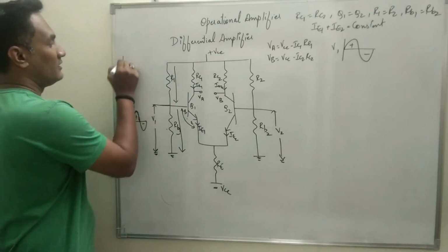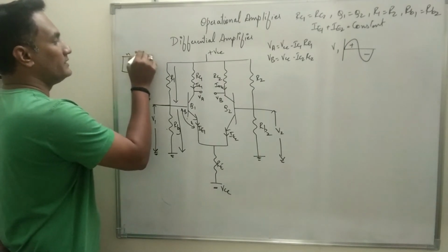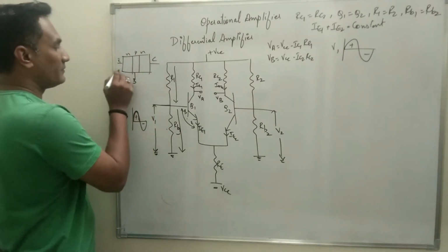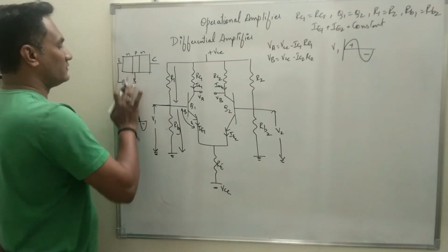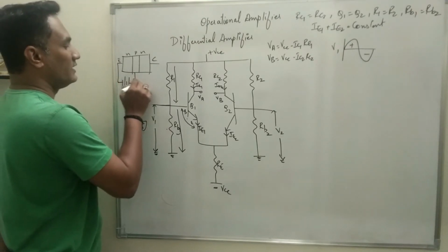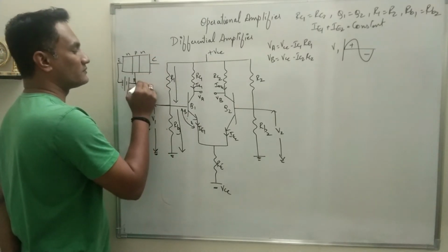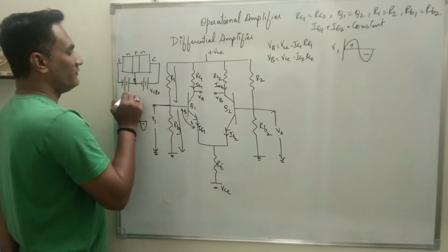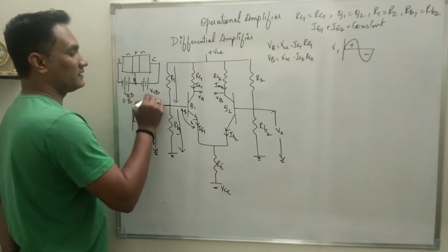Let us try to understand through transistor operation. Okay, so this is your say NPN transistor, this is emitter, this is base, this is collector. The emitter base junction should always be forward biased. So for forward bias, the polarity should be like this: negative, positive, negative, positive. Okay, and the base collector PN junction should always be reverse biased. So the polarity should be like this. This is called VCB, this is called VEB, that means the forward bias. This is the forward bias voltage, this is the reverse bias voltage.